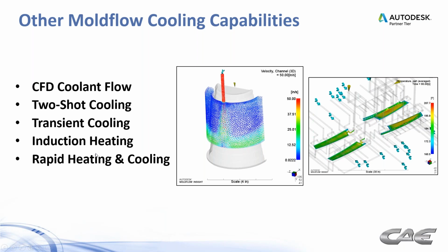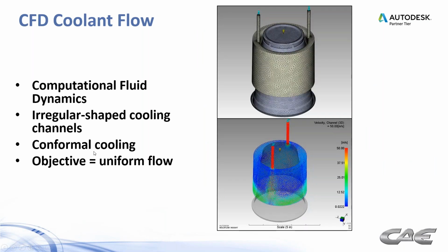All of these different types of cooling analysis, we'll call non-conventional cooling, can be simulated in Moldflow. We'll tackle the first three here. First one's CFD coolant flow. CFD stands for computational fluid dynamics. Why does that matter? It really boils down to the modeling of the cooling channels.